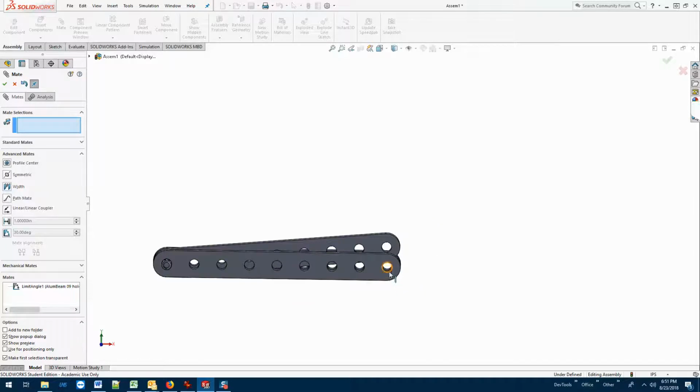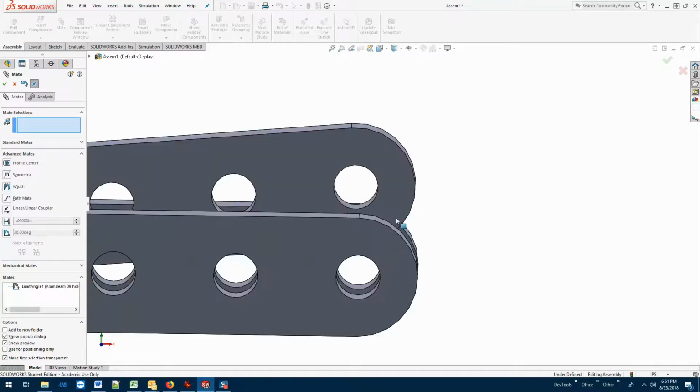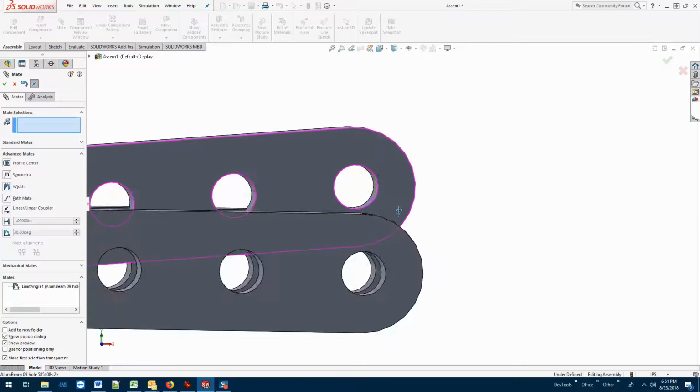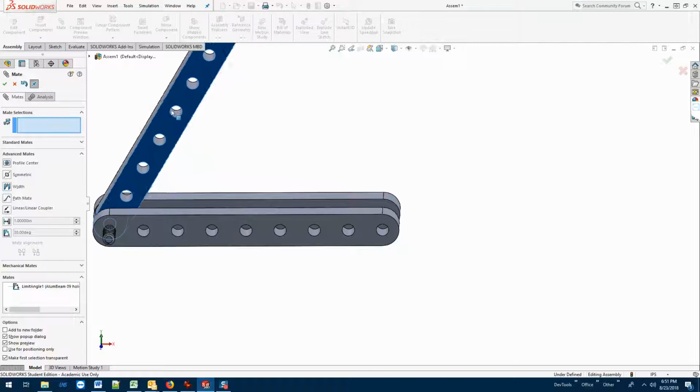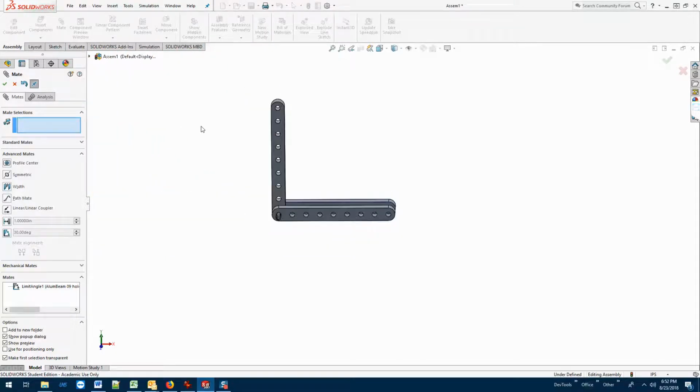And boy, that would be perfect. If I had a screw right through this hole right here, it'd be like this thing is being stopped right there by that screw hole. Maybe a couple of extra, maybe 4.5 or something would have been more perfect. But then when I try and bring it back, I'm stopped at 90 degrees. Okay. So now we're starting to see not only how we can allow for movement inside of our SolidWorks assemblies, but also how we can limit that movement.